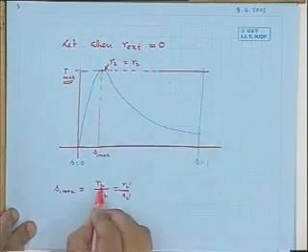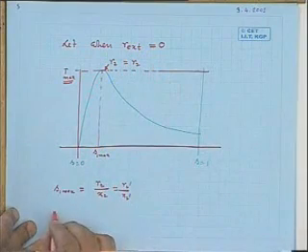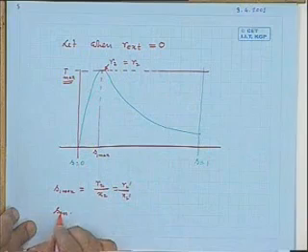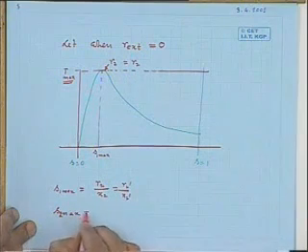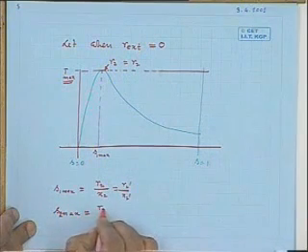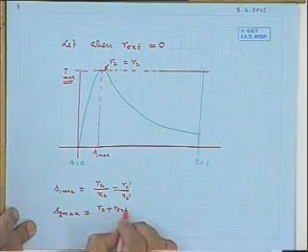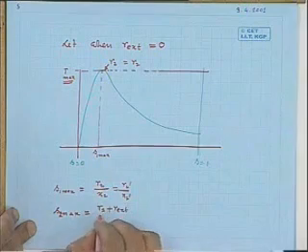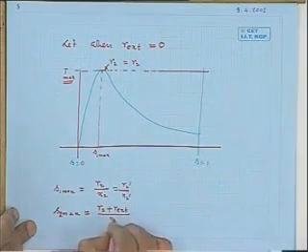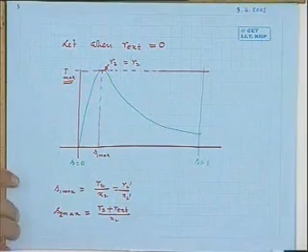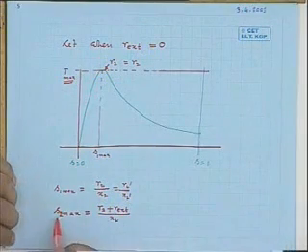Now suppose the rotor resistance is increased to R2 plus R external. The slip at which maximum torque will occur, let us call it S2 max, will be equal to R2 plus R external, which I have added per phase in the rotor circuit, divided by X2. The leakage reactance I have not changed.